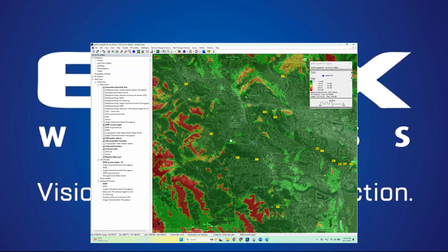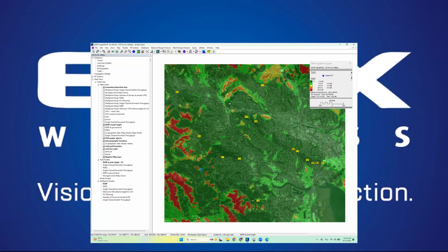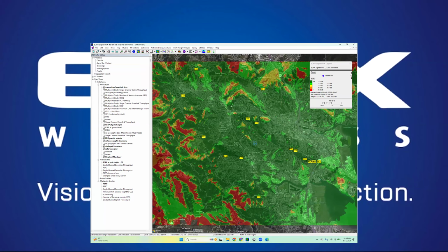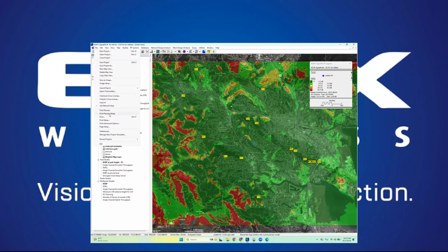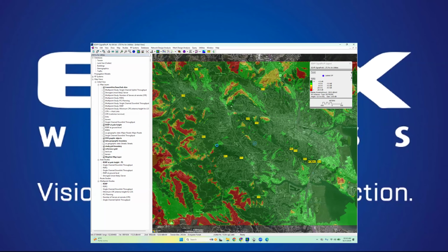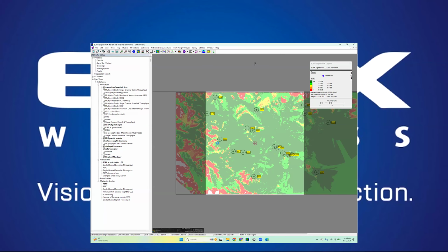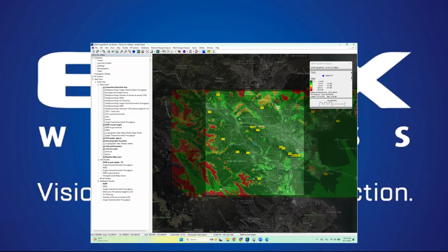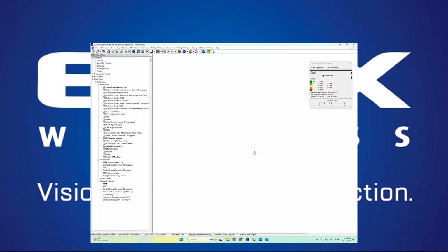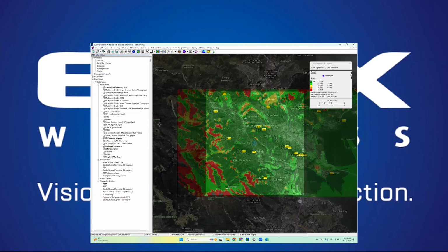And then if I want to see what is going to be included in the map window, there's kind of a disconnect potentially between my screen resolution and the resolution and DPI of that document. So this print preview mode I can use, and based on the document size and dimensions I have set up, I can sort of zoom in and out and get this situated the way I want, and then save that out to a PDF.